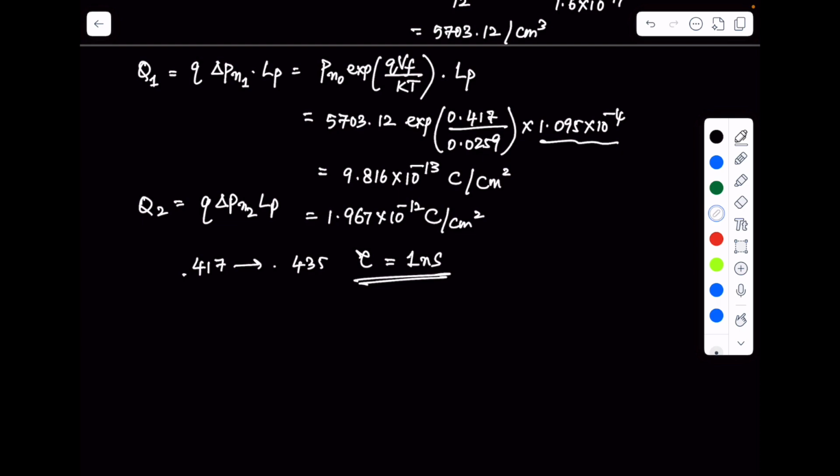And if you look at the charge density, it is essentially going to be exponential. So if this is the end of your depletion region, this is how your charge density is going to look, right? And this is Q1, say, and as you go, your Q2 is going to be right here, right? And you see that at x equal to 0, you have that higher increase due to higher injection. At x equal to infinity, both of them are eventually going to die down to 0.